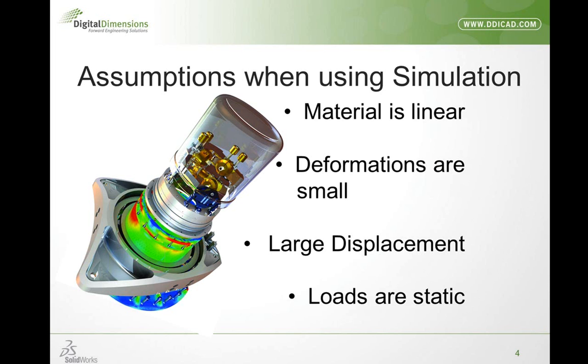If they're not small, the software will give us feedback so we can go in and run this large displacement mode, and then after that, do a true nonlinear study.